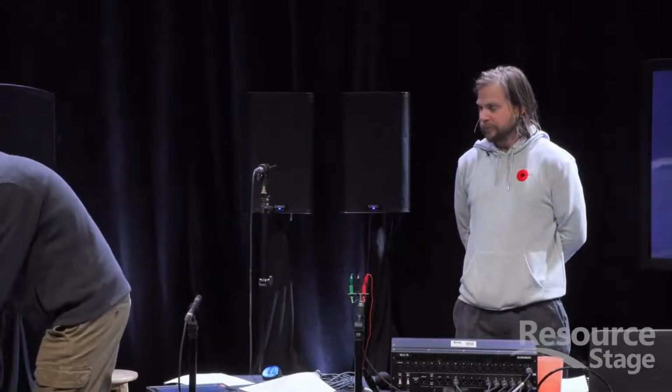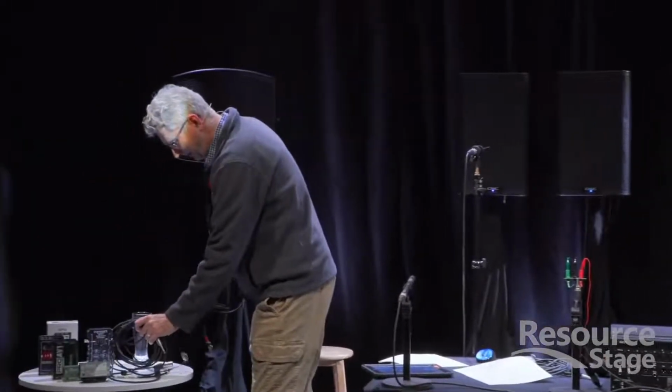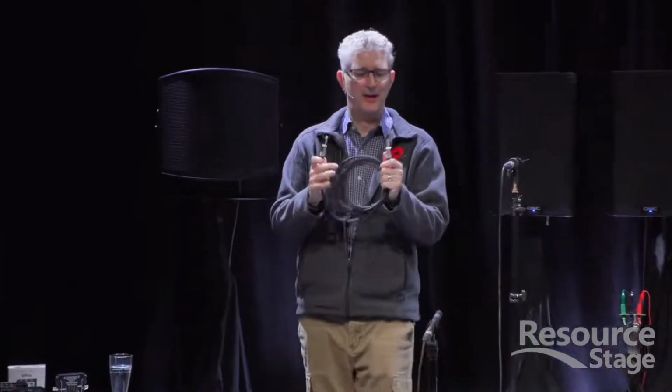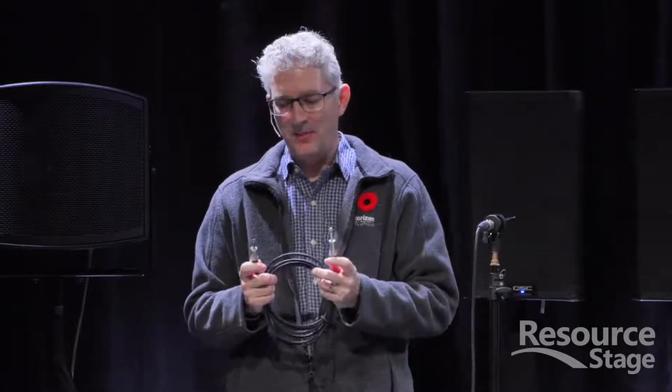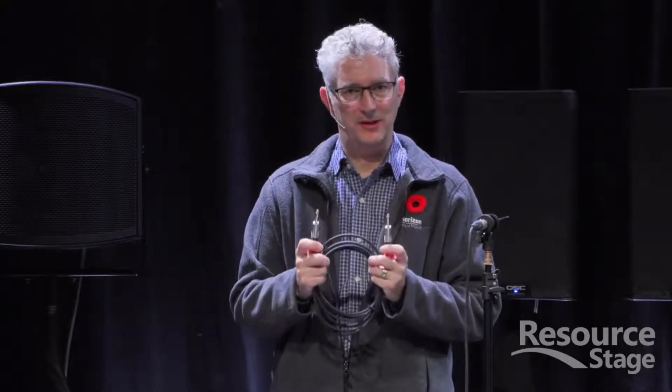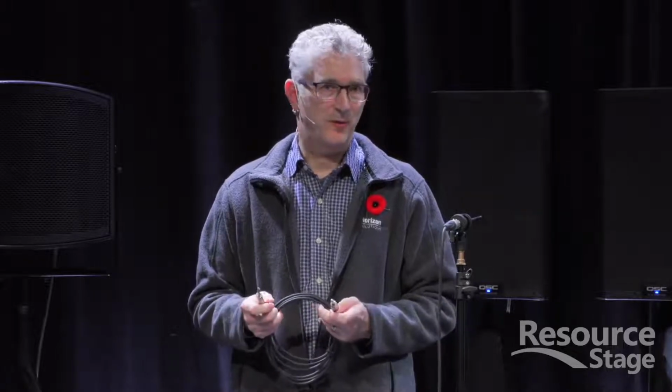Okay. So a speaker cable is a tip and sleeve like this one. It can have 1/4 inch connectors on it. These days, mostly it's Speakon connectors, which are a lot more robust. But they are a tip and a sleeve, or actually two conductors. They're usually a higher gauge than what this is. This will be maybe 22 gauge, maybe 20 gauge, whereas a speaker cable will be 14, 12, 10 gauge. So it's a lot thicker and a lot more robust.